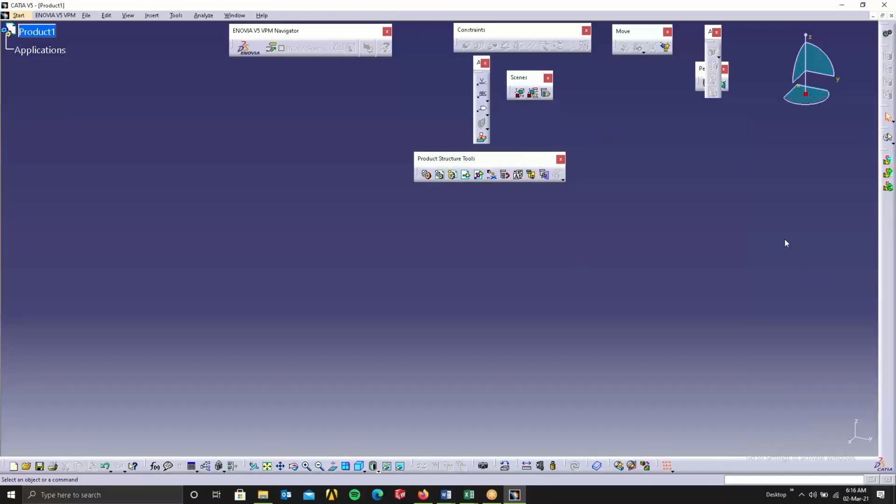So in drafting, we show isometric, as per the standard ASME Y14.5. But in the 3D model, when you are doing operations like putting a hole or finding the edges, at that time we make it trimetric for our ease of working. In drafting, there's no need for the inside lines and everything. It is just to show the manufacturing person how the reference 3D model is going to look.